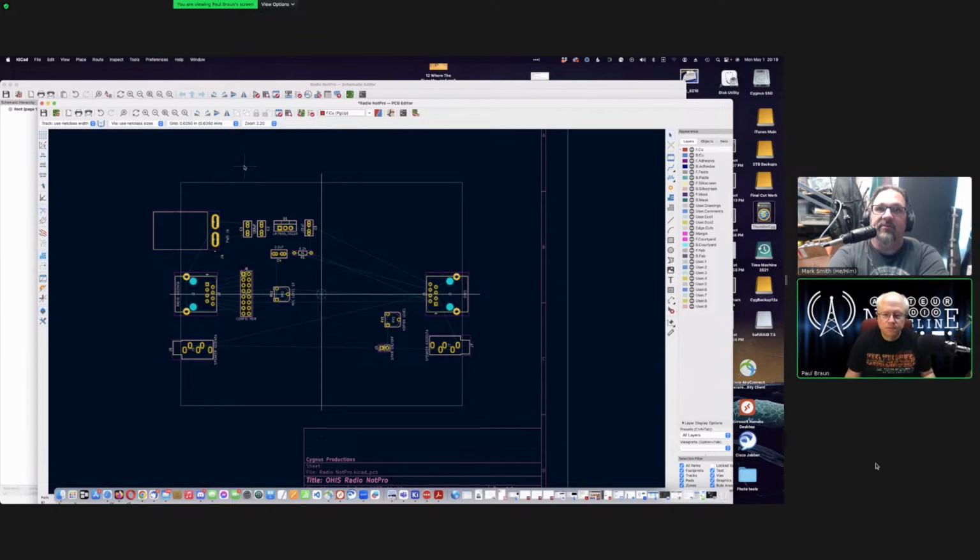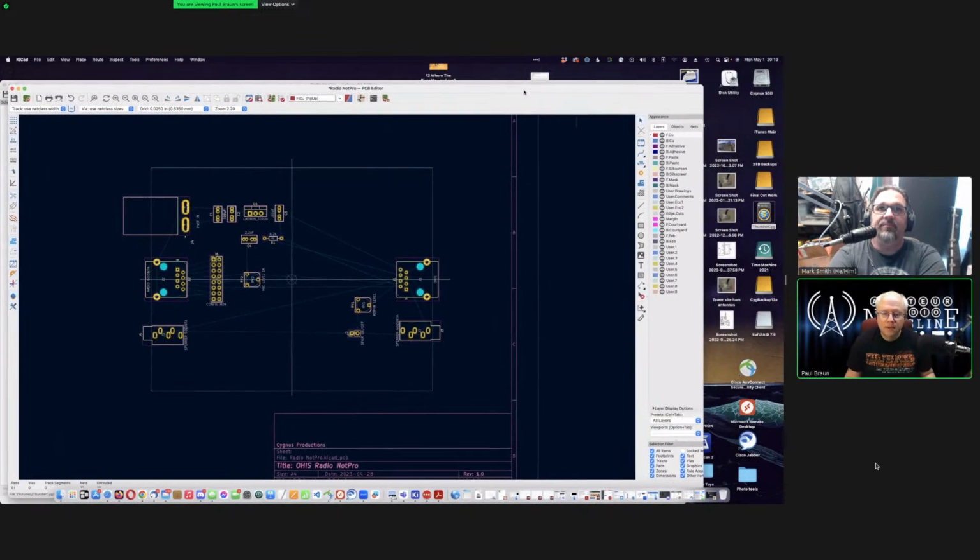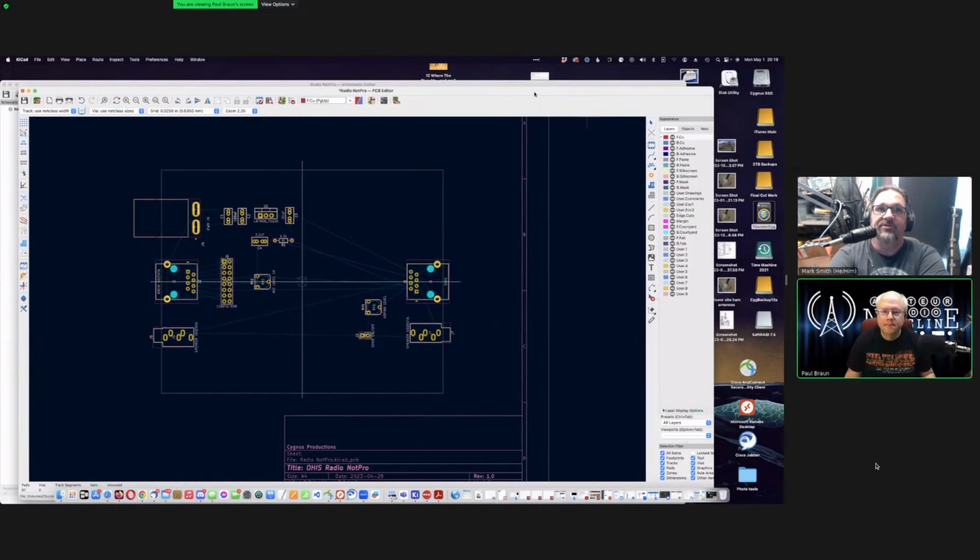So then, you probably want to lay down a copper pour over the entire board. So we got to go up here to front copper. It's the tool immediately beneath the yellow circle, which is your vias. Nope, over on the right side. Are you madly hitting Control S all the time? Yeah, I am.